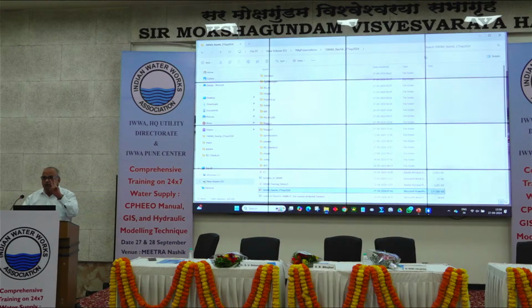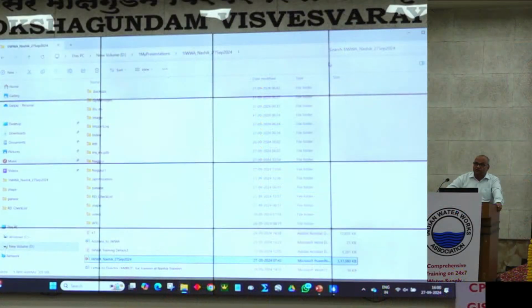Calibrations can be done in two ways. It manipulates the C value and calibration is done. Another way is the cross-sectional area. So you have to mention it, and then after calibration, those must show the same readings. Otherwise, it has no meaning. Till now in India, people are not doing the calibration. Therefore, this hydraulic modeling is used only for the purpose of deciding the pipe diameters.